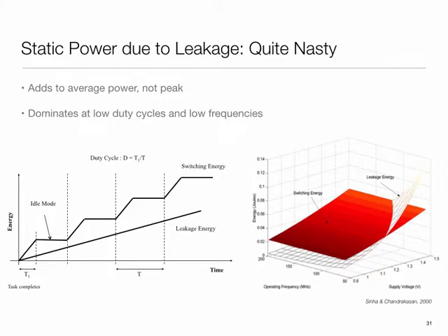I have the same n instructions to do. In one case I do it more quickly, n clock cycles done very rapidly; in the other case, n clock cycles done slowly. In the slower case, you are going to integrate the effect of leakage power over a longer time period. So I have the same number of clock ticks, but I have stretched them out.